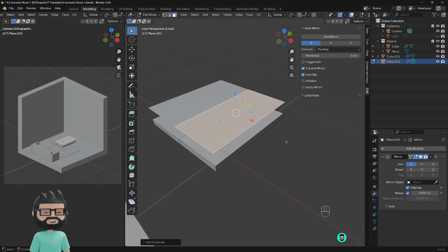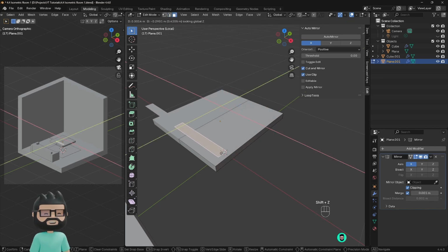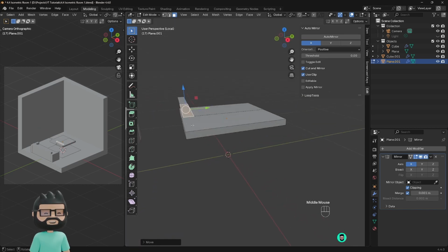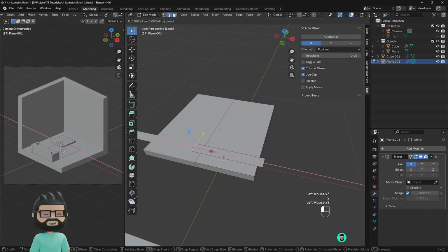Now to make a leg, you need to scale it down and scale it from here as well, but you will notice that we cannot actually move it to this side without having it connected here. So we actually need the leg just to be here, but we cannot actually disconnect it from here because the clipping is on. So just turn off clipping, select this edge in the edge selection mode, and now you can move it to the side.